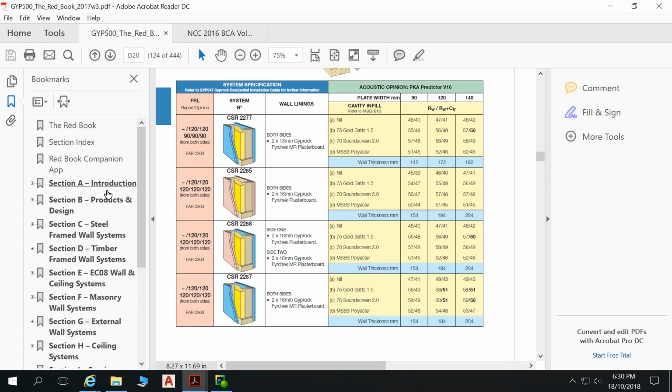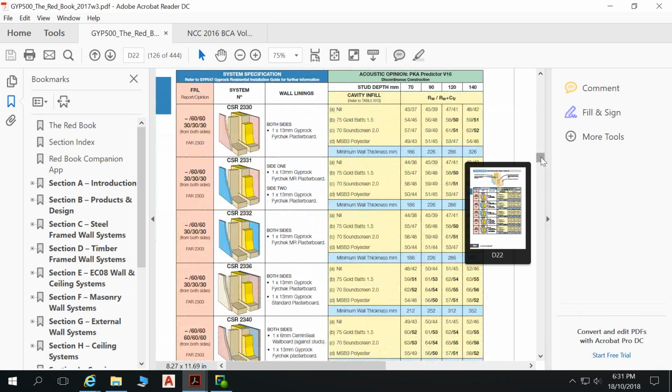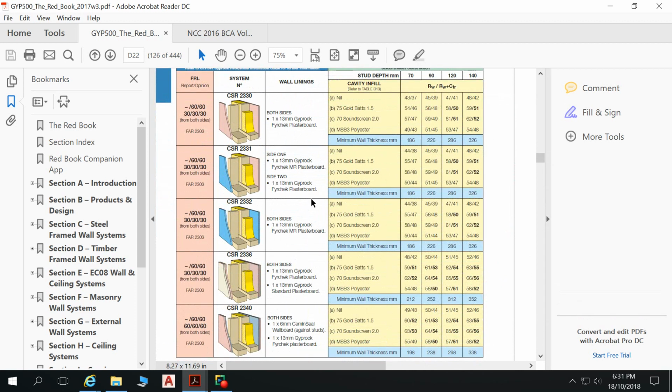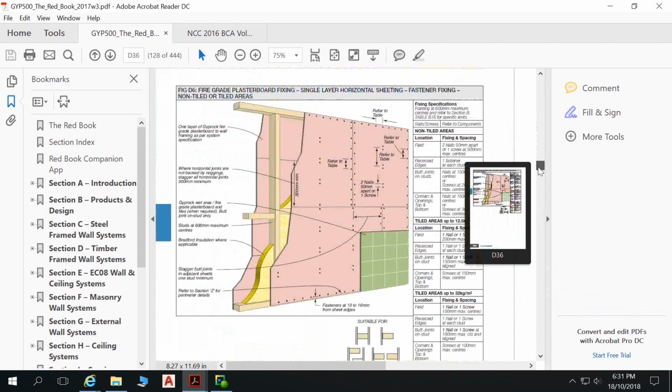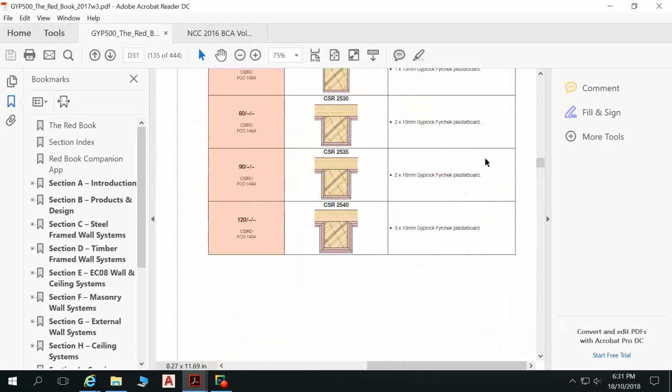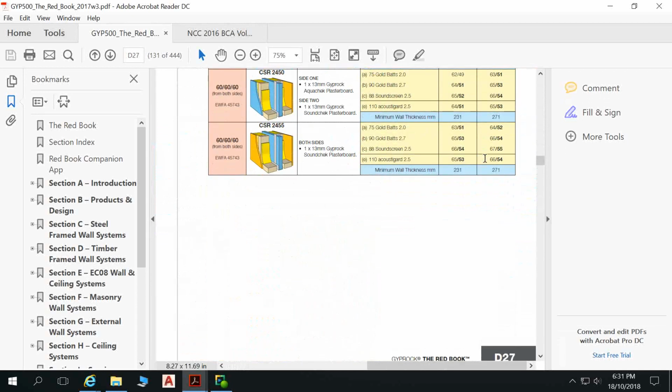Within these details, they've got this red for simple fire check and this blue for moisture resistant fire check. Has the same properties for fire resistance, but moisture resistant, that can be used in a bathroom. And so produces 120 minutes of fire resistance, etc. And then if we go down, these are double stud systems. So we were looking at staggered studs before. These are double stud systems, etc., etc. So those tables give you some fire resistance levels for your various different situations.